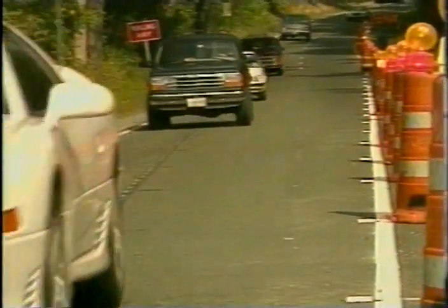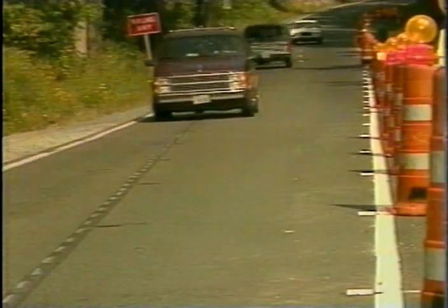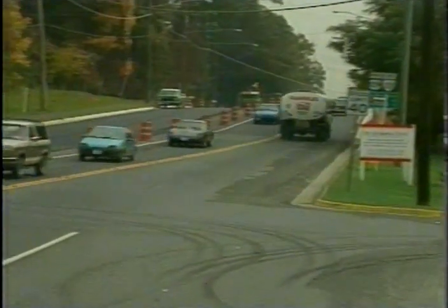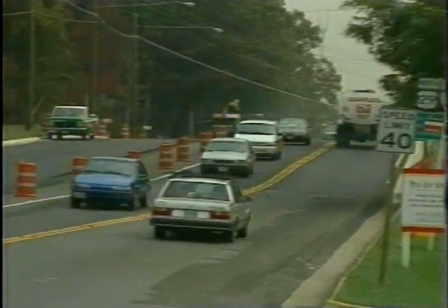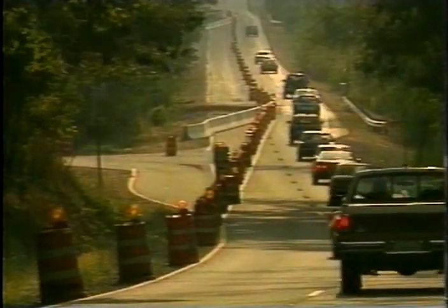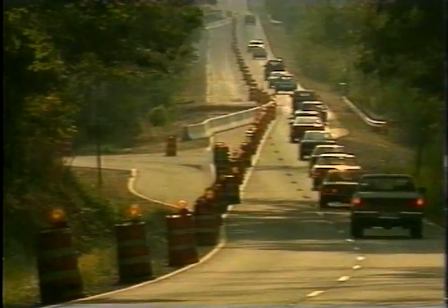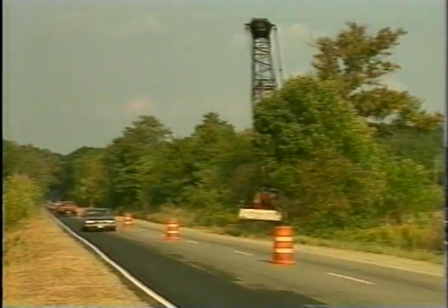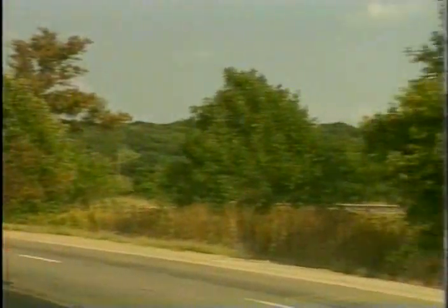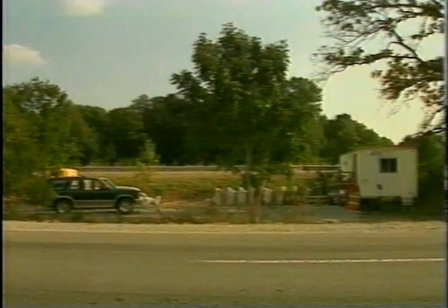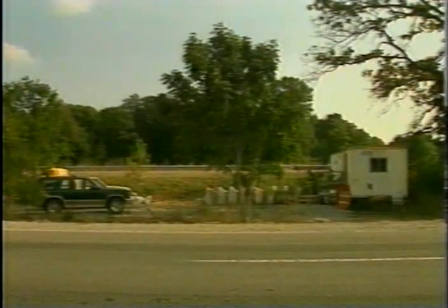A second principle is that traffic movement should be inhibited as little as practical. The best way to do this is to schedule and stage work operations in a way that minimizes driver exposure to unexpected situations. Also, avoid abrupt changes in roadway geometrics, such as dropped lanes or roadway transitions, that force drivers to make rapid maneuvers. Don't forget to provide for safe operation and storage of work vehicles. And remember, drivers will reduce their speeds only when they think they have seen a real need to do so,